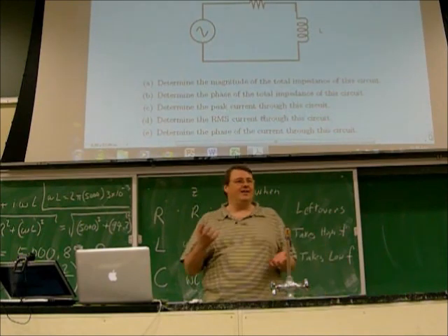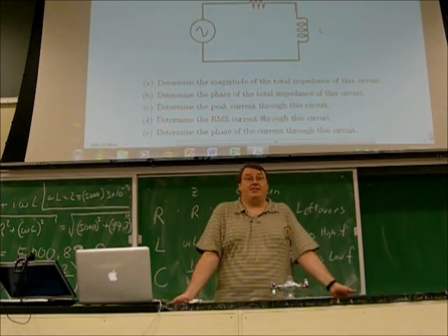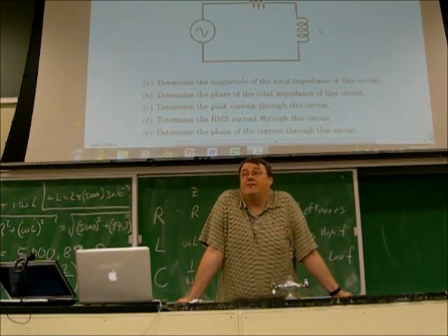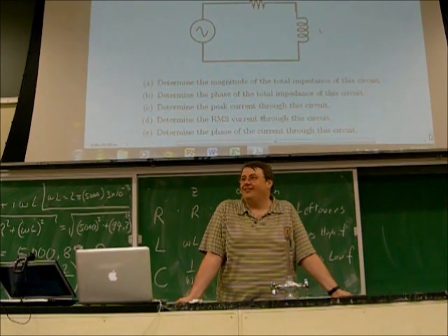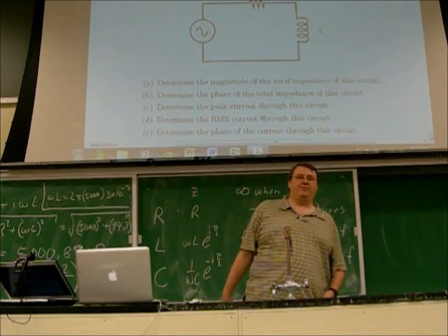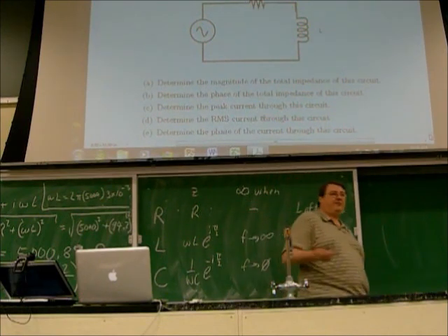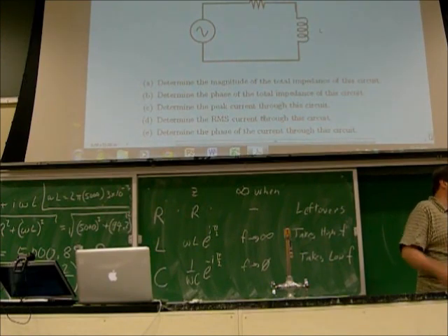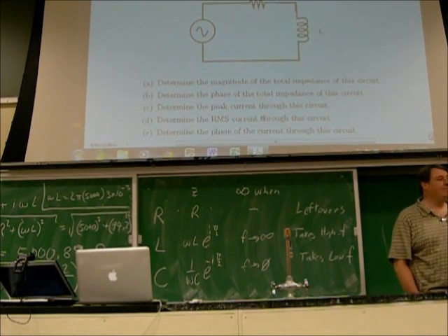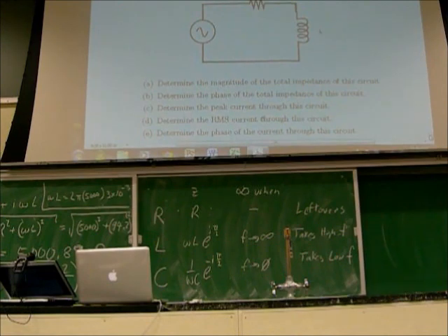Yeah, about the same size. If they were exactly the same size, the phase angle would be 45. And what did the phase angle turn out to be? 41, because you just won a little bit with the resistance. If they were 50-50, you'd have a phase of 45. But you had 120 versus 106, so you had a phase of 41. Okay? Everybody follow? So, starting